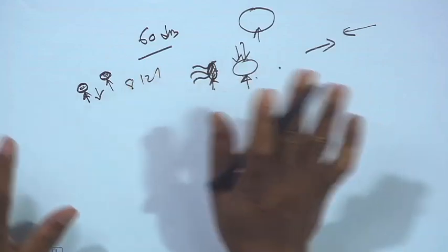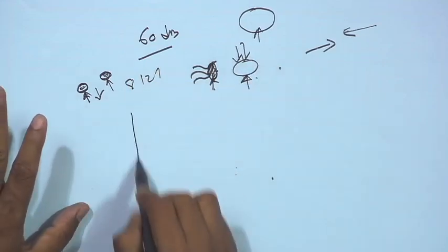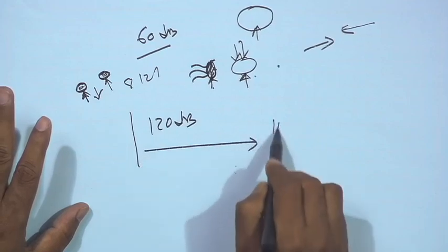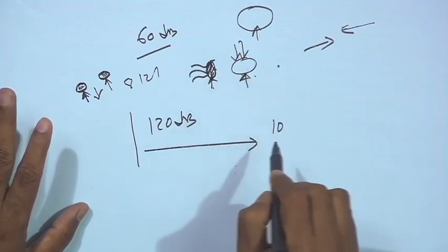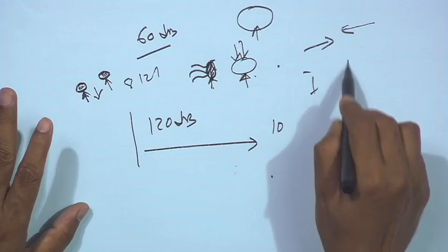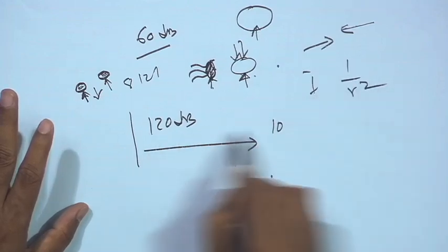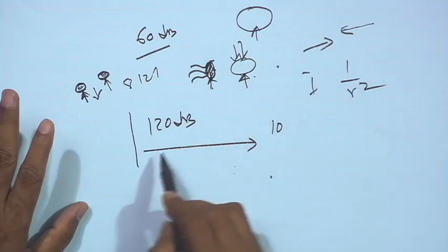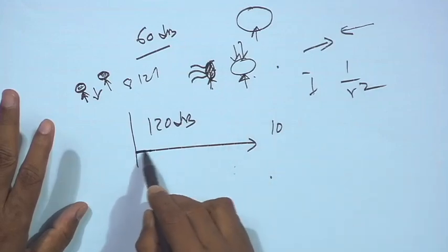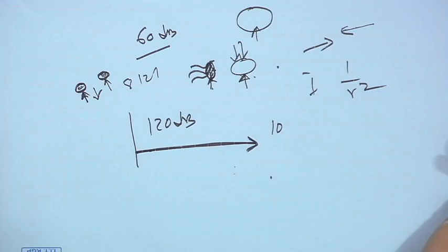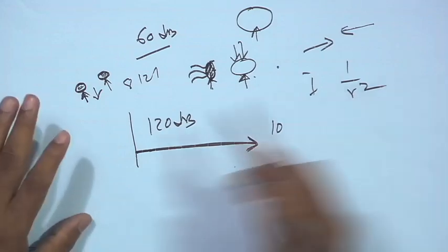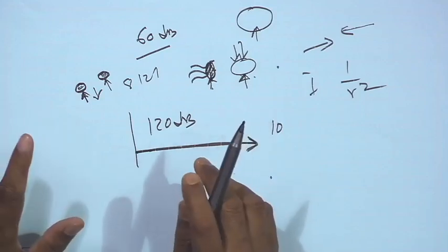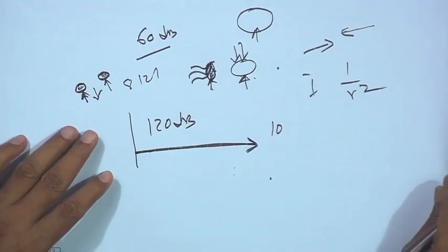So, there is sound propagation, you know that even if a source produces 120 dB, if you are 10 feet away, then you know the 1 by r square. So, I is reduced in 1 by r square form. So, every doubling of the distance, it is 6 dB down. So, being away from the source at 10 feet will reduce the sound intensity, but do not always expose yourself to a large sound, so that your ear sensitivity is not lost.